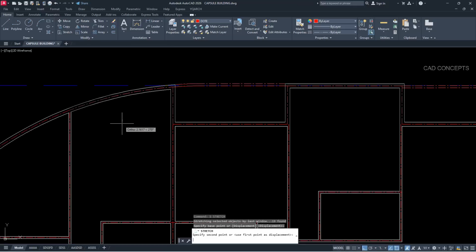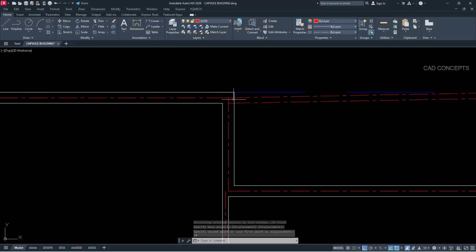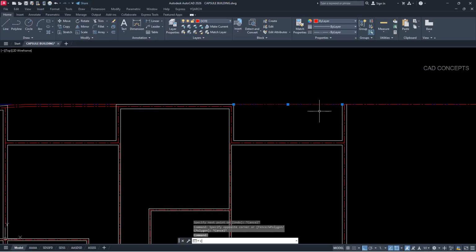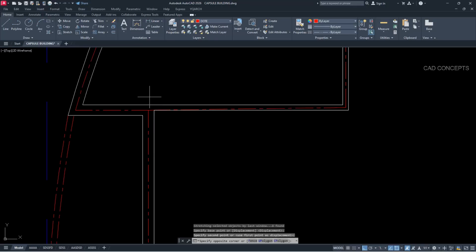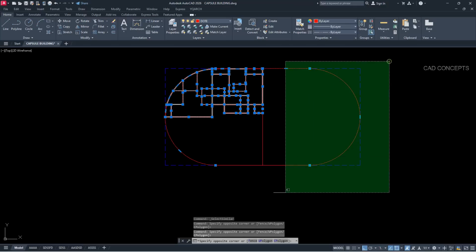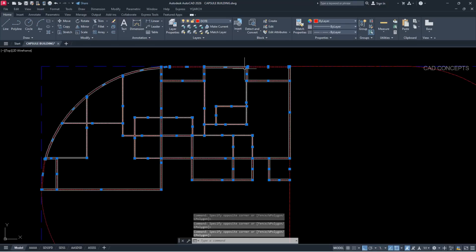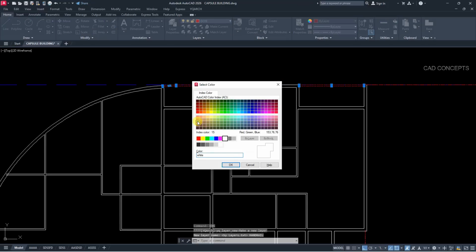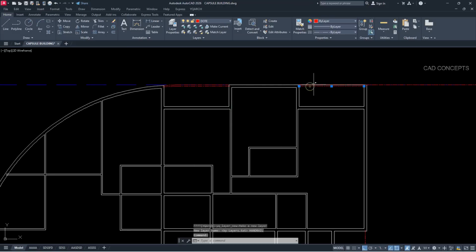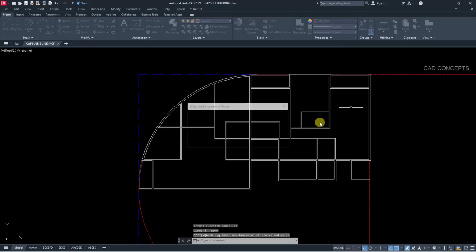So this part, fully stretch with our building line. And same here also. Offset 10 centimeter inside. This is exactly our handrail. Let this wall stretch 5 centimeter inside. Now these center lines are not required. Create new layer, handrail. You can directly create the layer. And change this layer into the new one, handrail.